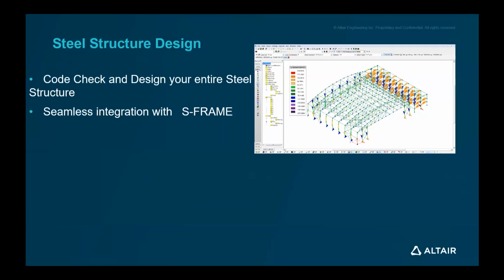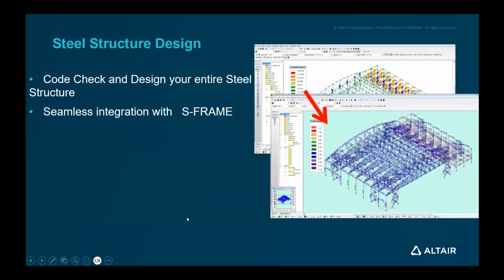Like I briefly mentioned, it has a seamless integration with S-frame. So you can model your full structure in S-frame, add different sections, analyze this structure, and within the same environment, within the same user interface, you can code check and design these elements, this full structure, obtaining utilization ratios and getting code detailings and very good reports of this.